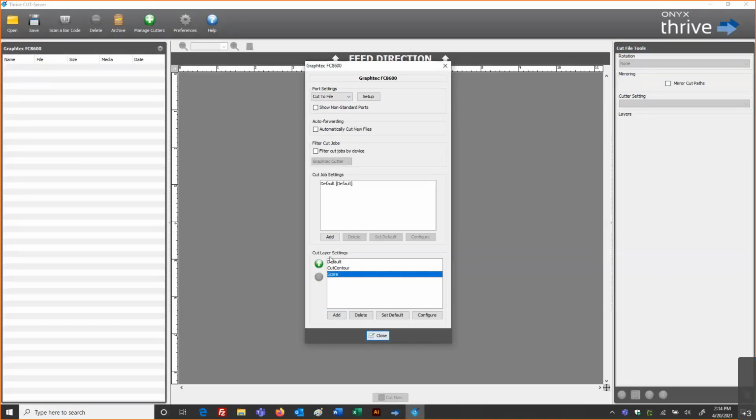There is a layer order to this. What will happen first, what will happen second, third, and last. If the term cut contour is representing the cut to go completely through the material, and score is meant to represent just the surface to cut through at the very center, what we might do then is move that score, that light cut that doesn't go all the way through the material, to take place before the cut contour, which may be a completely through cut scenario all the way through the material.